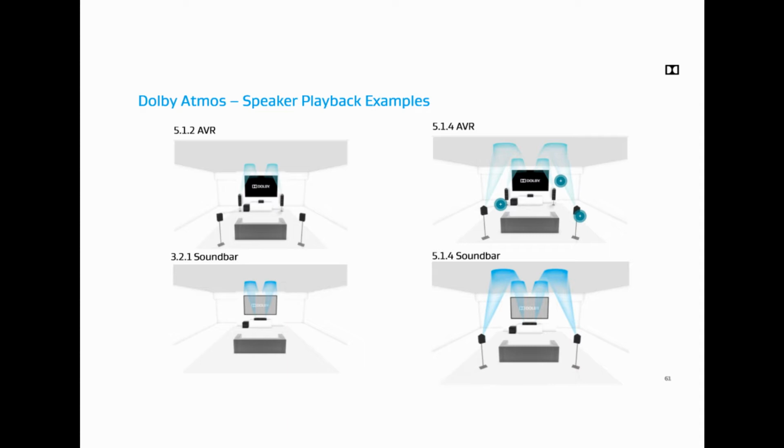And it works surprisingly well. Again, like spatial coding, some of these things on paper, you talk to an audio purist and you go, really, will that work? And this idea actually came out of an internal hacking competition that we had, where ideas are kind of brought forward. They used speakers with door stops angled. A door stop actually had the right angle in this particular demo scenario. And there's a small amount of HRTF processing there to kind of give the effect of the overhead shoulder bounce.